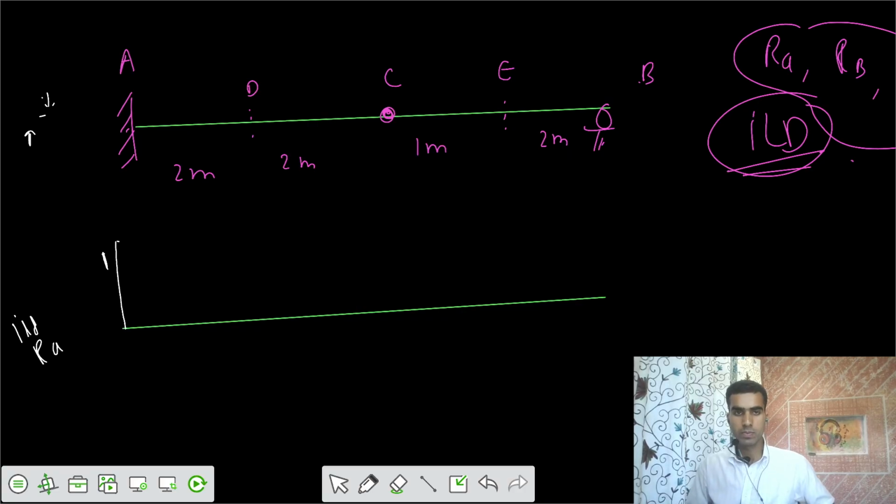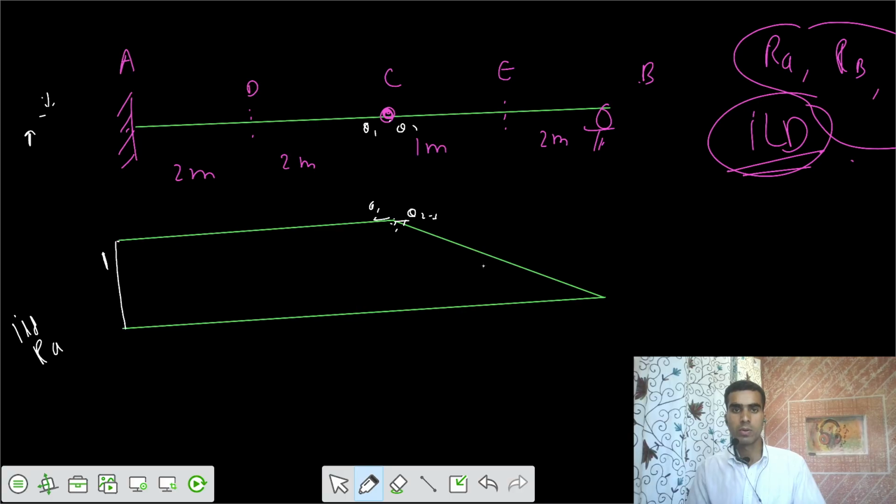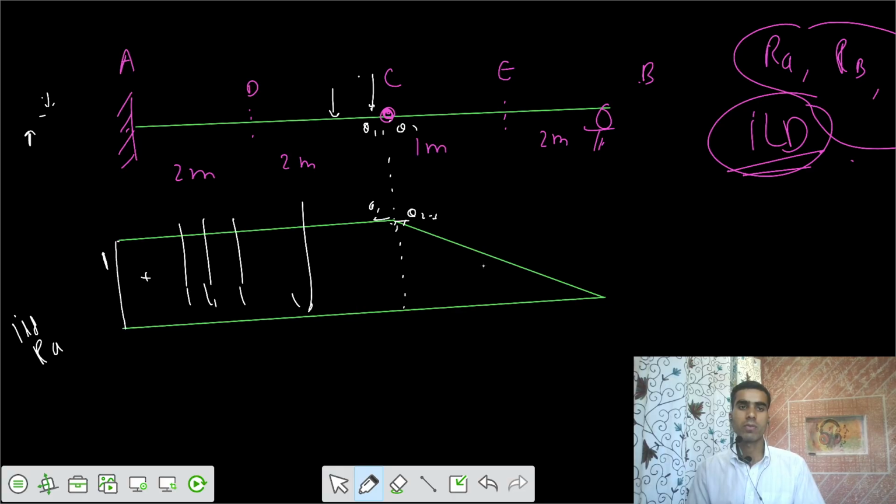Let's have that one also. So up to this point, there is linear variation, a straight line. After that, it goes downwards. This is because the internal hinge can have a different theta from this side: theta 1 equals 0, then from this side, theta 2 has some value. So as long as the load is up to this point, we can have a reaction of 1 at all times. On all occasions when the load was in this part, you would have the same value of reaction, that is reaction 1. That means the entire load is taken by the support A. We call it a parent support.